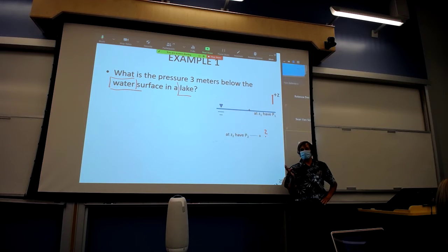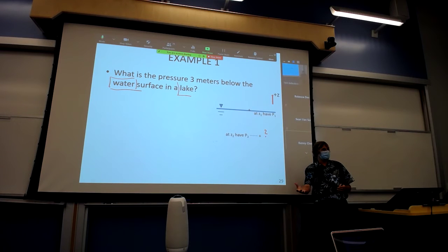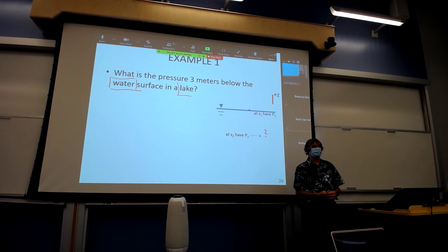My guidance to you in the past, and will continue to be, if in this course a temperature is not given, assume it is at room temperature, 70 degrees Fahrenheit, 20 degrees C. When you leave here, it is incumbent upon you to know the temperature range of the systems you're looking at. So if you're talking about water flow in pipes underground, that's probably going to be at the average annual ambient air temperature, wherever you are. Okay, so in this course, either the temperature is going to be given, and if it's not, room temperature.